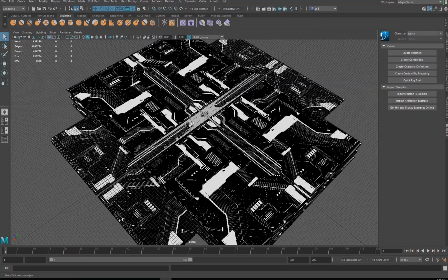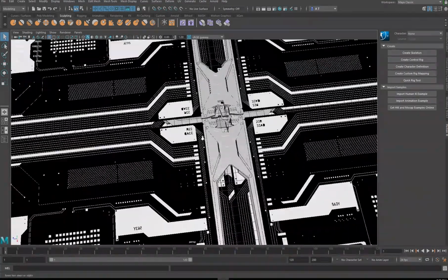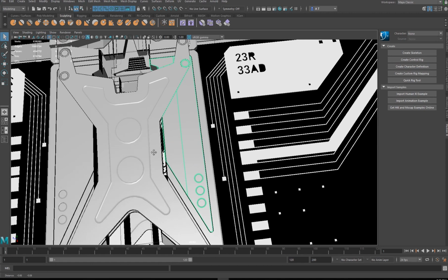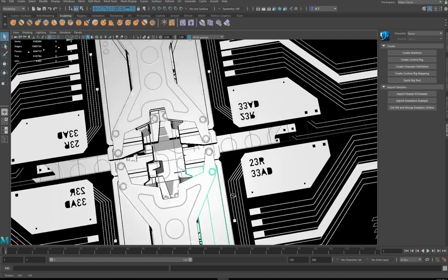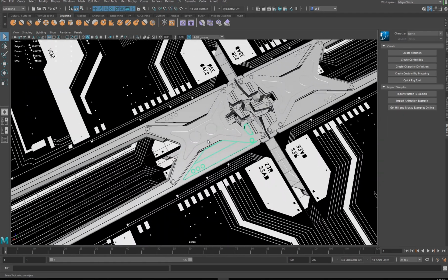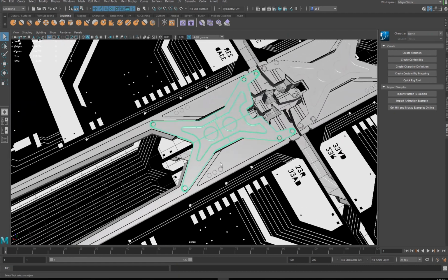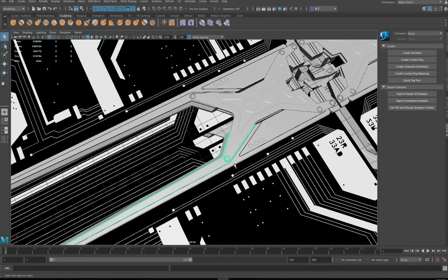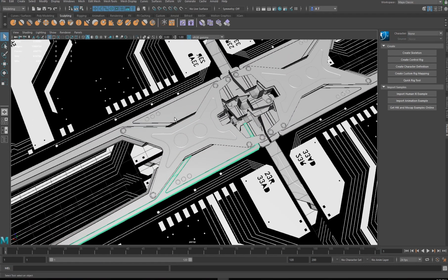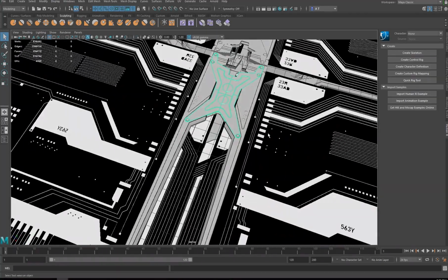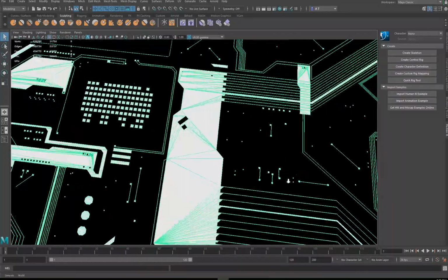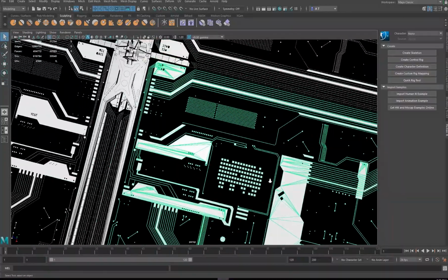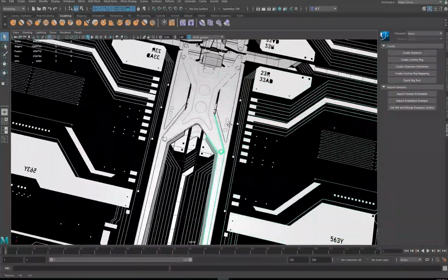And here I'm inside Maya, right? So I imported these bits inside Maya, and when you import a STEP file, you get NURBS objects on input, not a mesh, which is fairly handy because if I go and convert it to a mesh, it's going to be like a 1 million triangle mesh. Then I imported this stuff from Blender, so you can see this is just the mesh, so it's triangles, next to the NURBS surfaces right here.